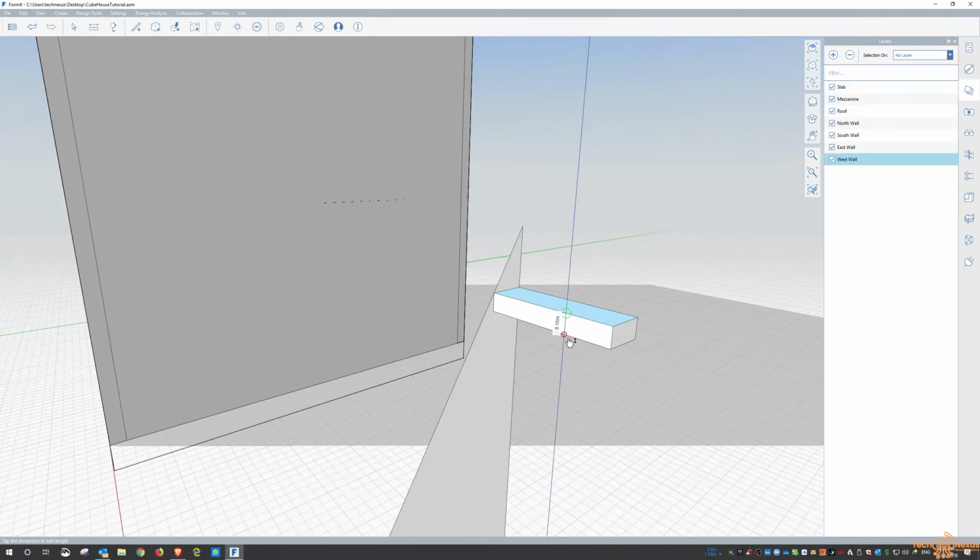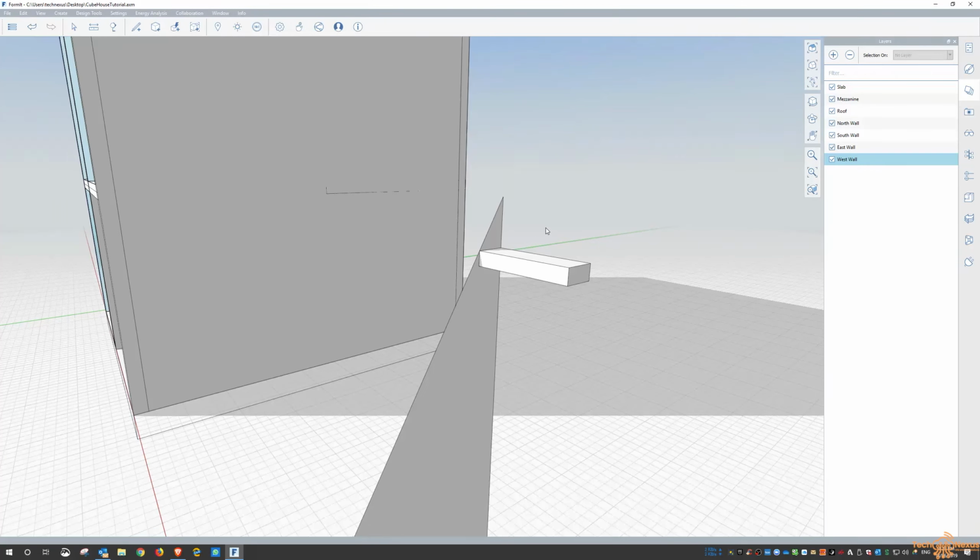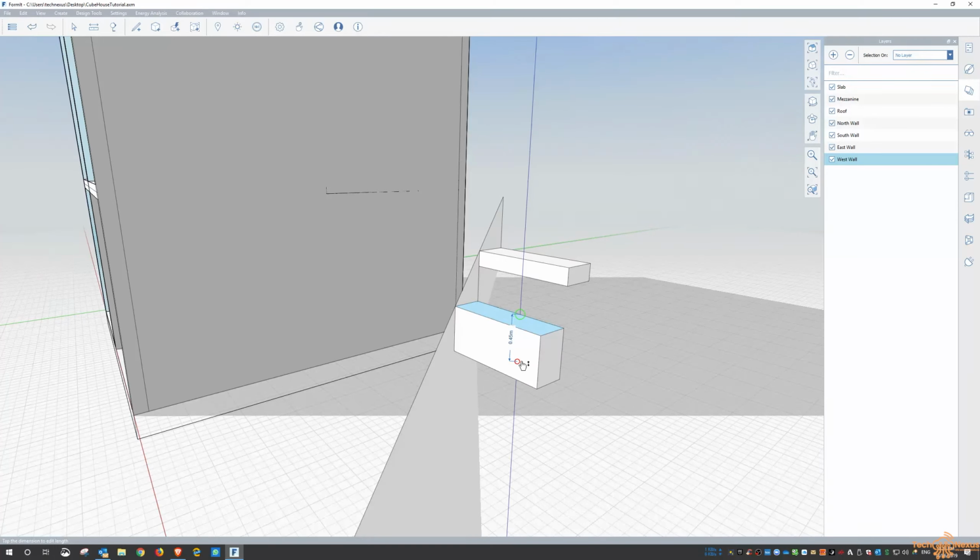And then from that, it's going to be 0.15 deep. So what we can do, similar to what we did before, is go through and keep, so if I say 0.5, 0.3, 1, 0.3, then come back and do the same, so extrude that, 0.15.